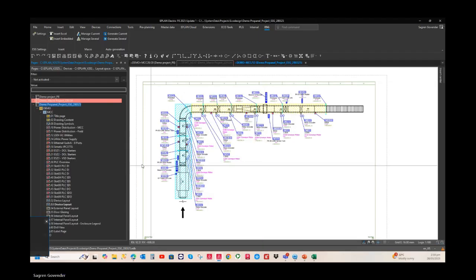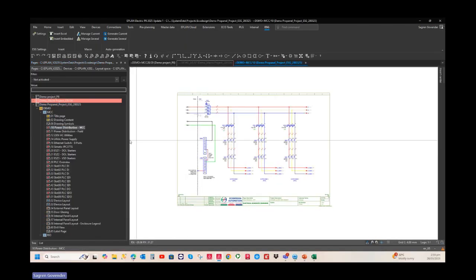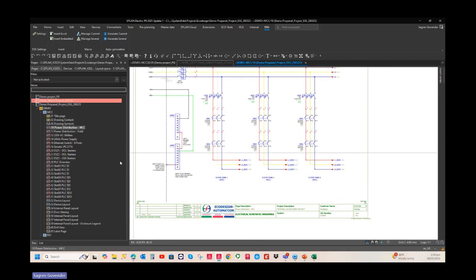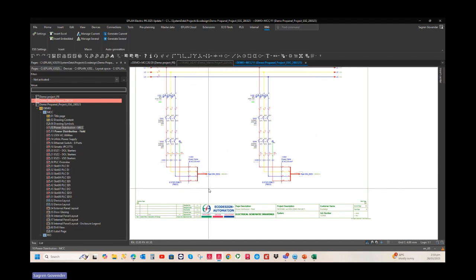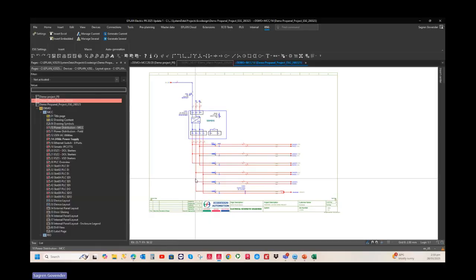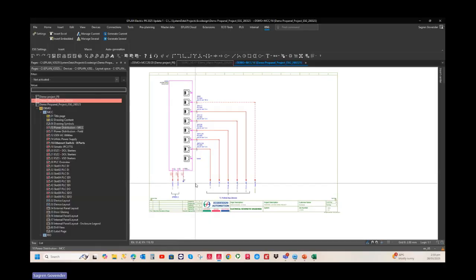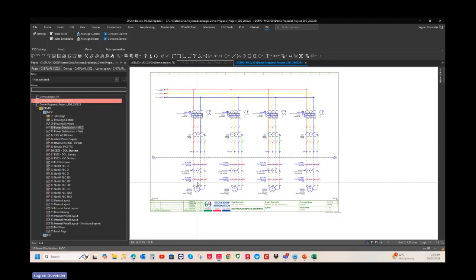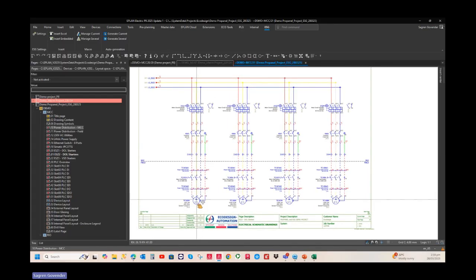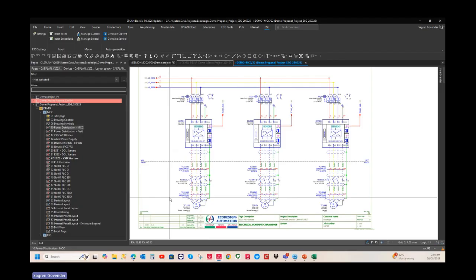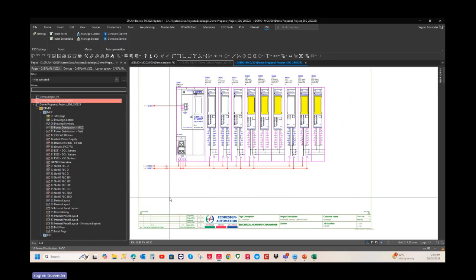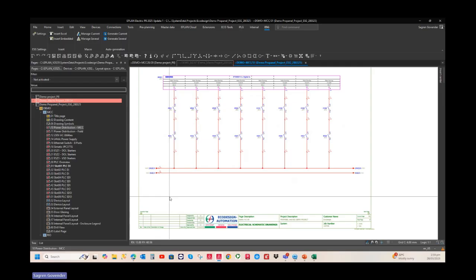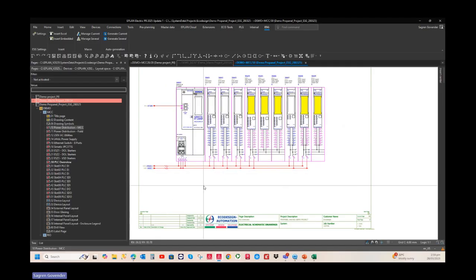Yeah. So within a minute or so, it's basically generated these drawings for me. So here's my power distribution for my MCC. I'll just page through this: power distribution to my field devices, my utilities page, power supply, Ethernet switch, HMI, my DOL starters, VSDs, my PLC overview rack. And again, I've downloaded these macros from the data portal. I didn't create any of these from scratch.